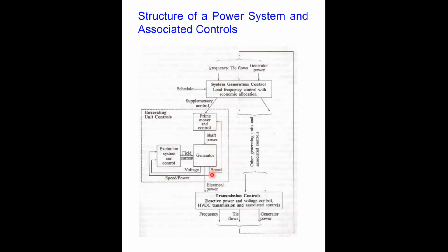And then if the system is interconnected through your network, then here comes the load frequency control, and sometimes we also refer to it as automatic generation control when we apply the economic allocation for the power plants, referring to the frequency control problem. So this is the complete structure of our power network, and the different levels of control action applied here.